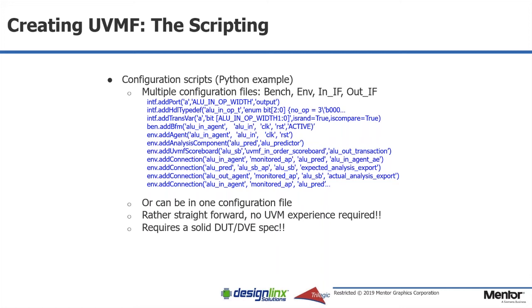The bench area allows you to add BFMs. In this line, bench.add BFM, we are adding actually a driver because the keyword active is part of that construct. If it was passive, it would be a monitor.